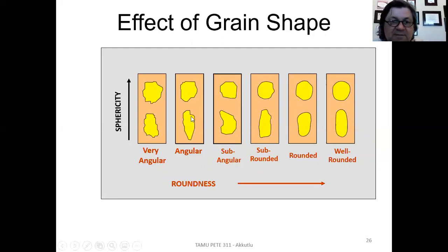But if you go to the left, now you have the same behavior, but now your sphere has more rugged surfaces, more angular features. How is the porosity being influenced by this? Well, it turns out that with increasing sphericity, porosity increases. So platy material, elongated material, gets compacted easily, so there's not much space between them. But as things get spherical, porosity improves.